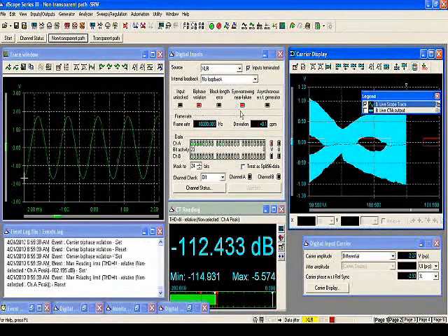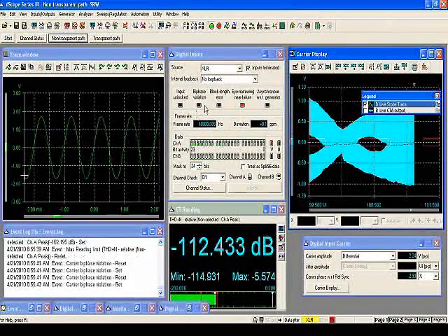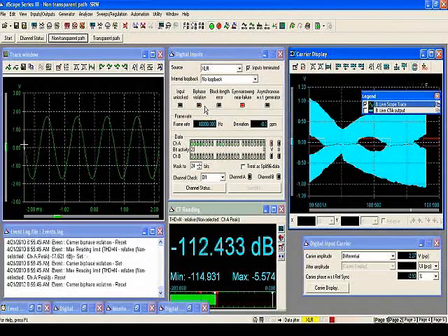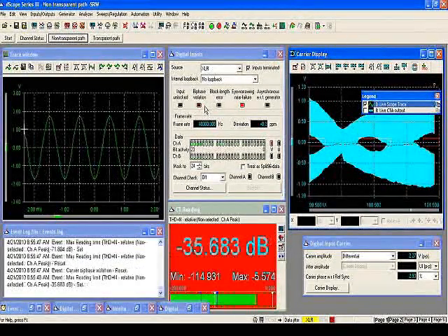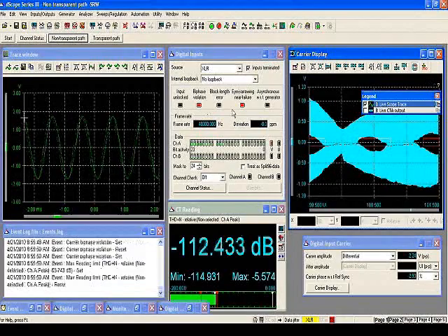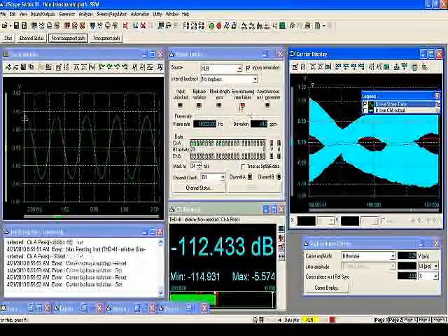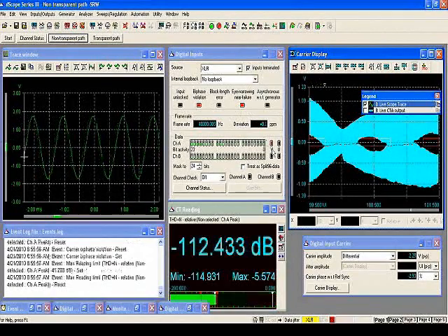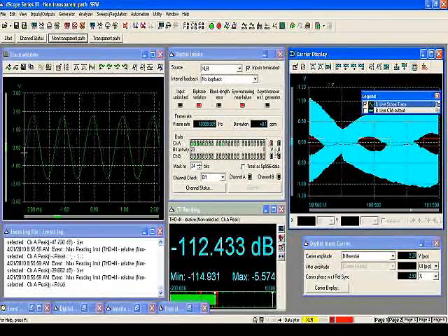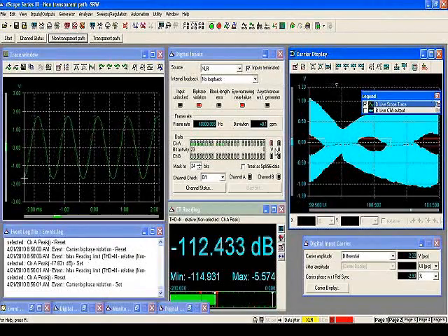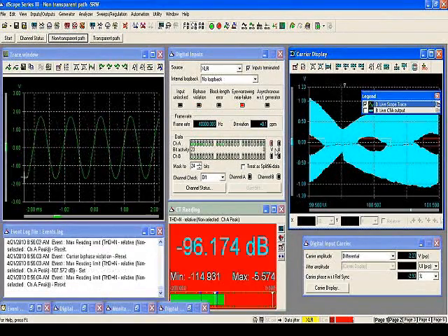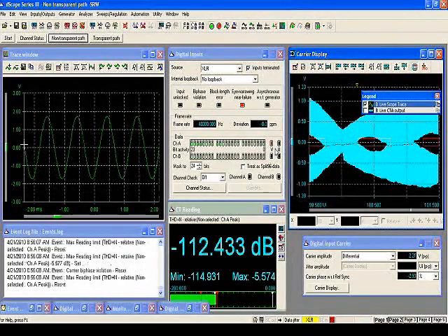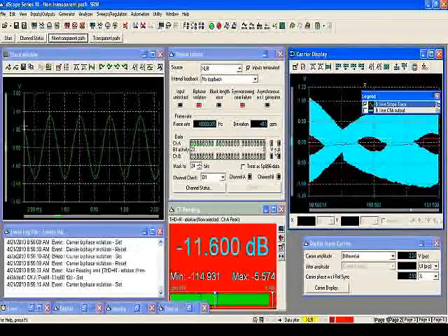But anytime you have a biphase violation, you have lost data or you have an error in data. Eye narrowing near failure, so we've got an indication of that. Of course, I left that validity bit in circuit, so we're still showing that error. All of this is being presented to help you track down where and why these pops and glitches are coming into play.